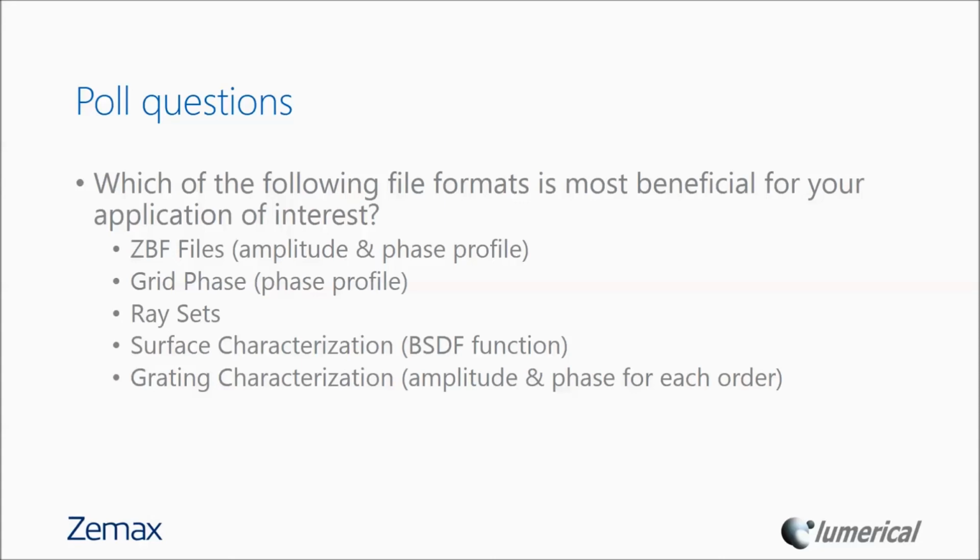Okay, and then the last bullet point shown here for the poll is talking about the fact that Lumerical can be used to characterize gratings and to calculate the phase and amplitude or intensity for each of the diffraction orders. So then this information can be fed into OpticStudio just like as described in the preceding bullet points.